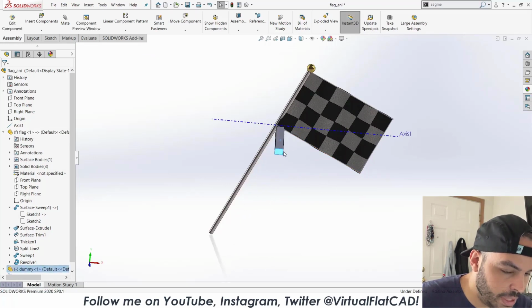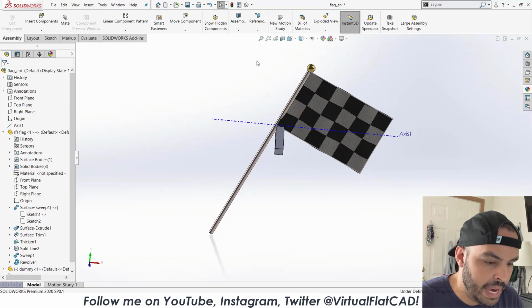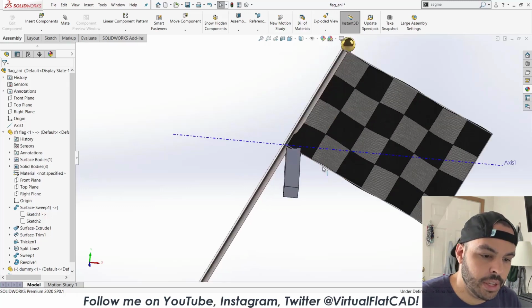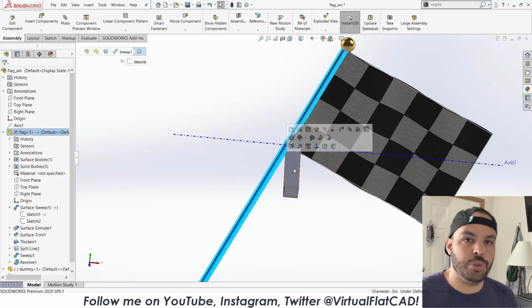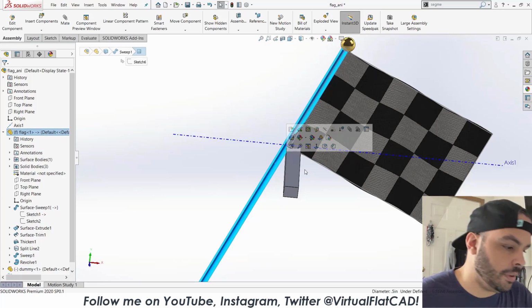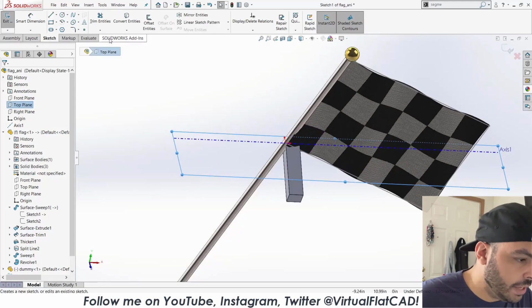I'm going to leave the dummy part showing. That's totally fine. But actually what I need to do is to pattern this. I think what I'm going to do is, you know, I don't really want to mirror it, because if I mirror about a plane, they'll be directly on top of each other and you'll see the two shafts crossing, whereas really I want one in front of the other. So we're going to create a new axis.